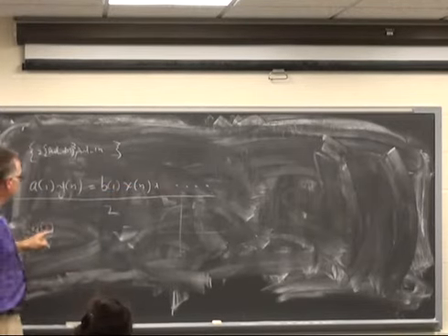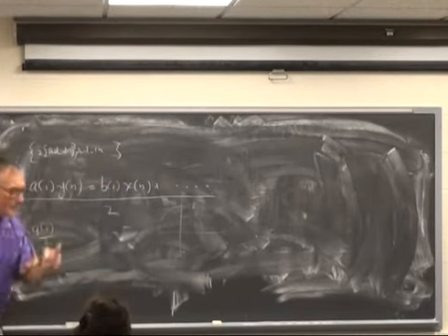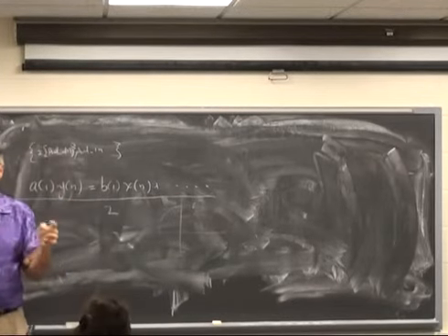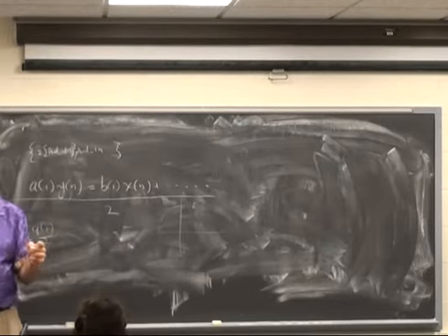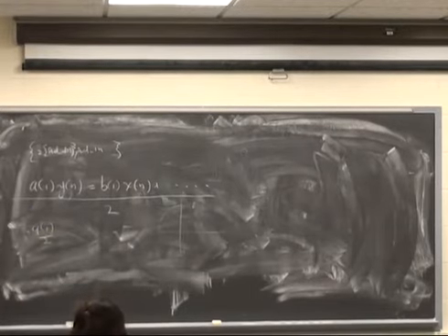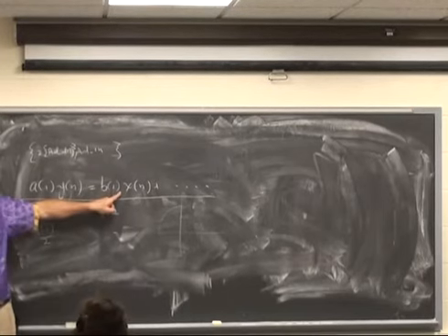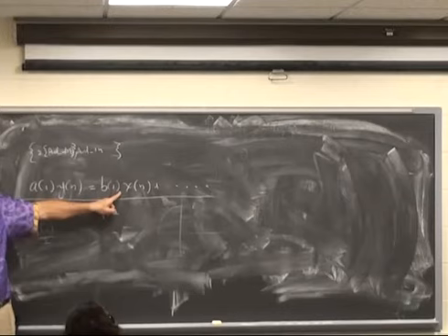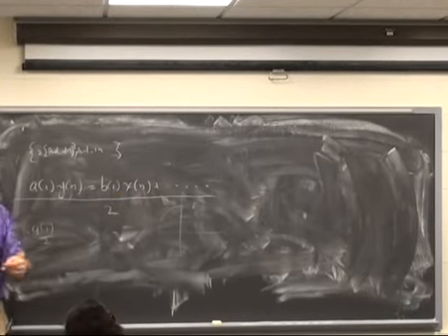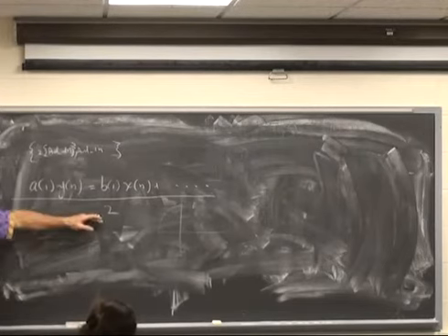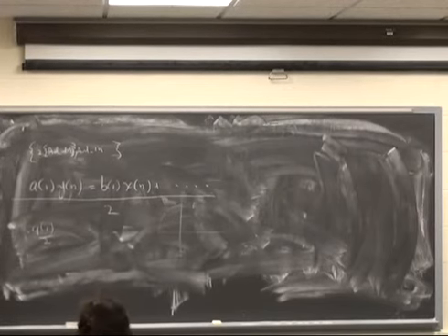And then the last step in the filter is you calculate this sum divided by 2, and then you shift 1 bit to the left. So you can avoid some overflow, because quite often in the filter there will be a fairly large product which is negative and a fairly large product which is positive, and those cancel to near 0, and then when you shift back to the left by 2, you do not get an overflow.